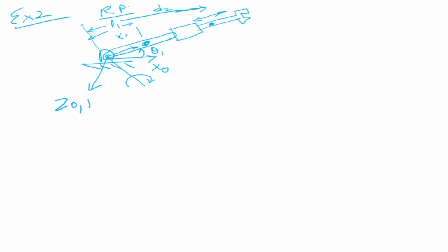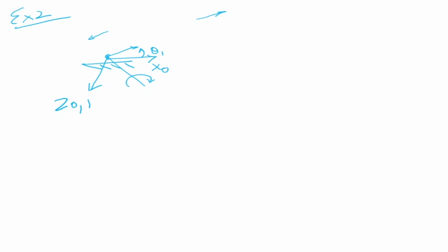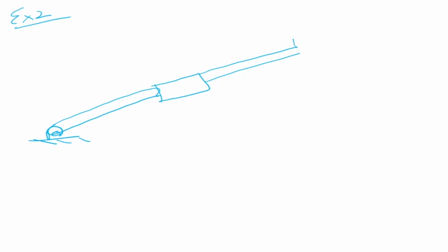So if you can visualize this robot carefully, this is looking very clumsy. Let me draw it again. When we are looking at this robotic system, let me draw it a little bigger because this is difficult to understand. So this is one link, there is one more link here, which is a prismatic joint, and this joint is moving front and back. Now it's better, I think. So this one is a prismatic link. The first one is a revolute link. So let me draw the axes z0, z1.